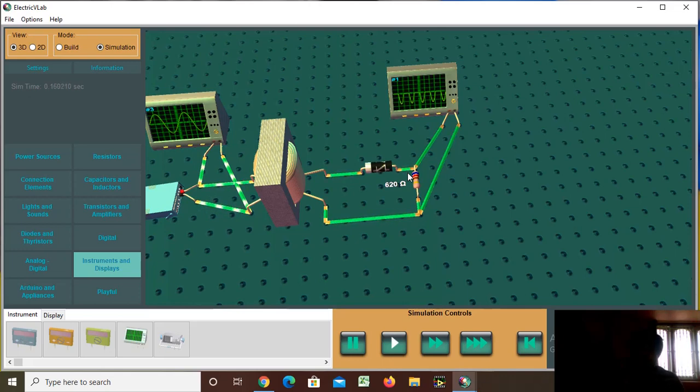In order to find out the efficiency and ripple factor, as I said, you just measure Vm, like 11.3, and use some formulas to calculate efficiency and ripple factor. You already derived efficiency and ripple factor in basic electronics. The simple calculation is there. Efficiency is PDC by PAC. If you write the efficiency equation in terms of voltage, efficiency will be equal to (VDC by VRMS) whole square.